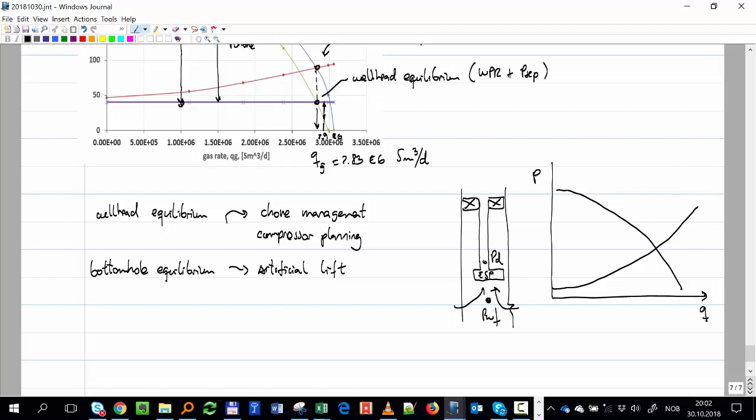Okay, and this will be bottom hole pressure and the pressure at the discharge. If I put no pump, the two of them are exactly the same. Okay, the two of them have to be operating here. Now, if I put the pump and I want to produce this rate, Q star, then the pump has to deliver that particular delta P.